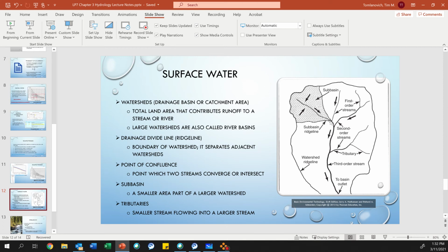So we want to figure out what's the flow there, and then the flow continues. The first step in watersheds is, okay, let's do our divide line, and your book does a good job of explaining this. Let's figure out which way that water is going to run and which stream that water runs to, or manhole, etc. That's the first thing you figure out.